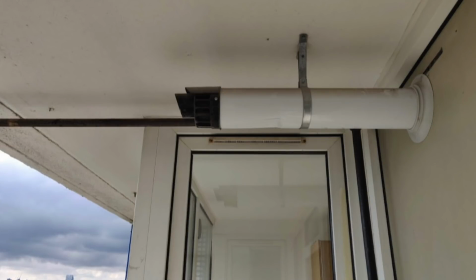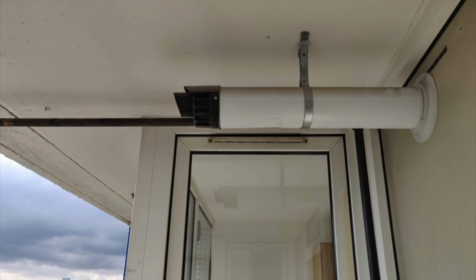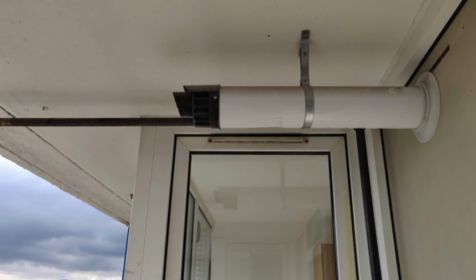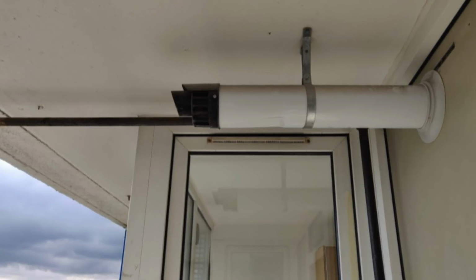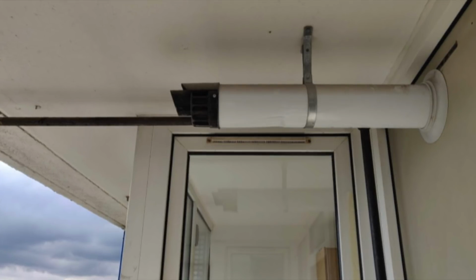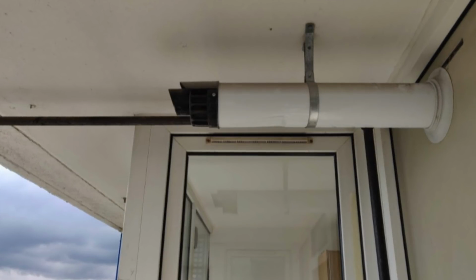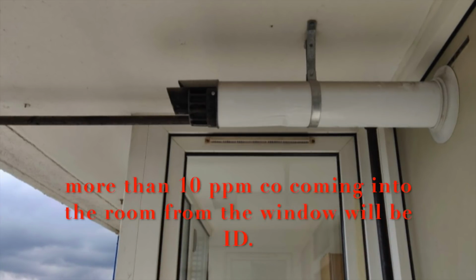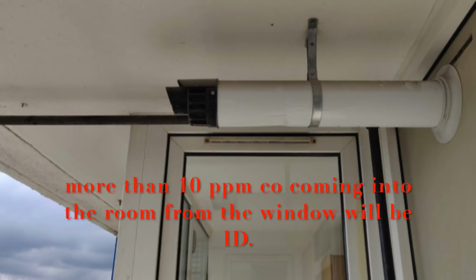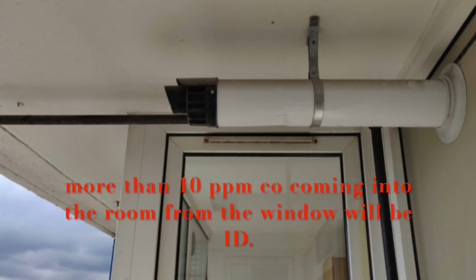So installations like this, they just take my words away. I am bewildered and staggered that somebody would install a flue system like this. Again, we've got a Baxi and Ideal sticking out through the wall. Again, would be at risk. They have clipped it, but this would be crying out for a balcony kit because there's an openable window right next to where the flue is. You can't really tell from this picture whether it's more than 300 away from this window, but there's not going to be much left of this porch when this condensing boiler runs for a long time.